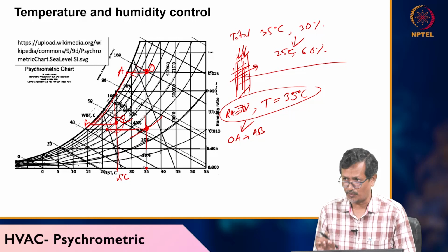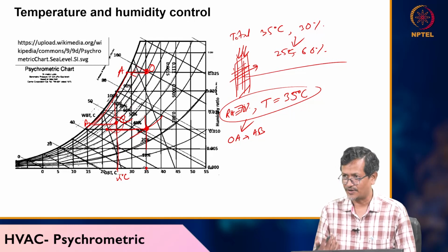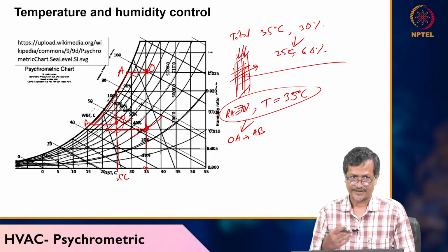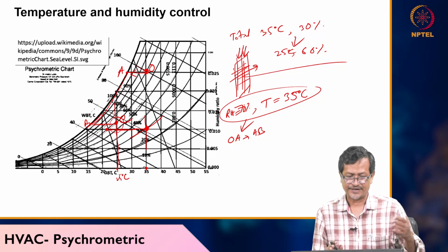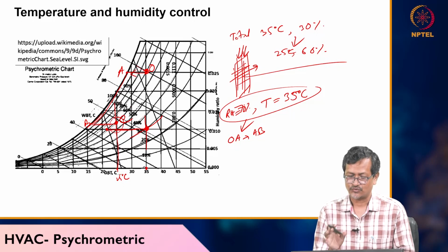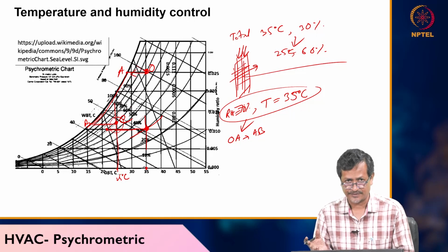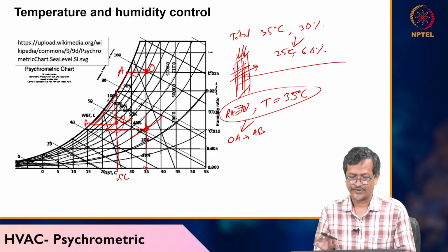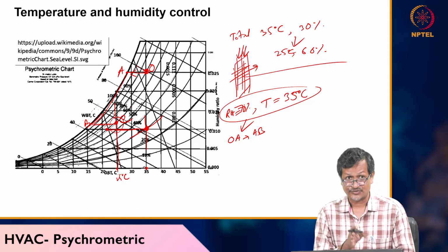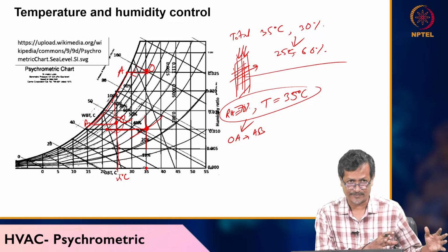But if you already have low moisture, then actually you cannot reduce moisture. In that case, you can add moisture. When you are adding moisture, you are making your room comfortable. So in North India, you can see lots of desert coolers. Desert cooler will be reducing your temperature and increasing humidity. But in South India, if you are using the same desert cooler, it will not help because it will be adding more moisture. So that will make your life more uncomfortable.